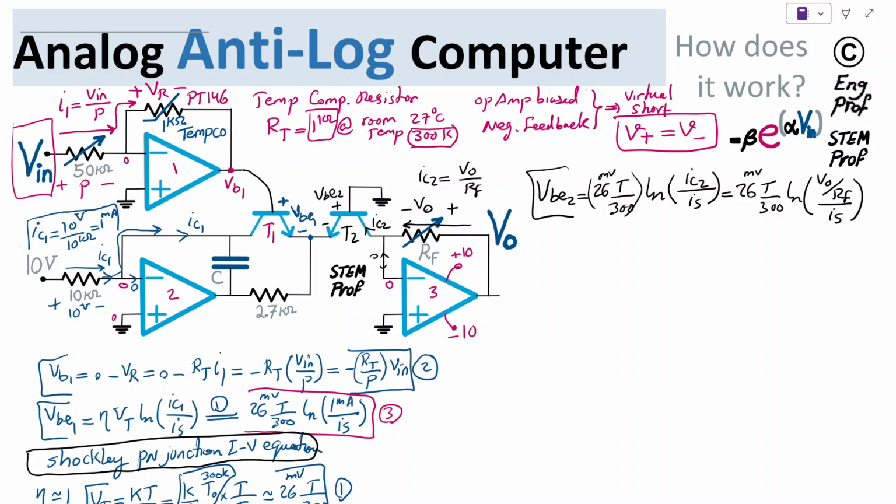So it's nice we found this equation number 4, but again it suffers from the same problems that we found before. We have a linear dependency on temperature. We have a worse dependency on IS, which is heavily exponentially dependent on temperature. So what else is going on in the circuit? Well, look at the common emitter here. There is a voltage E, which is the voltage of the emitter of both transistors. I can say VE1 equals VE2. Obviously we have the same common emitter, so I can substitute for these.